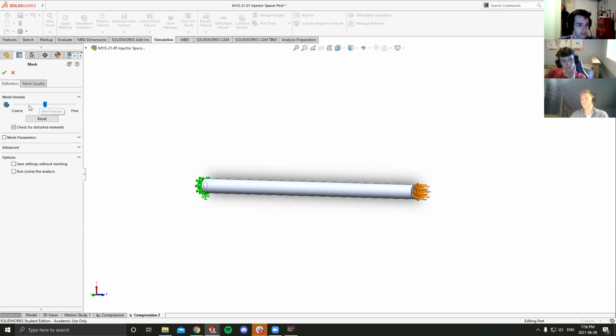And so we can set right now... setting up our mesh is relatively simple. Basically, we just select the coarseness or the fineness of our mesh, coarser being less accurate, but also less computationally intensive. The finer it is, the potentially more accurate the simulation will be, and many more numbers need to be crunched.